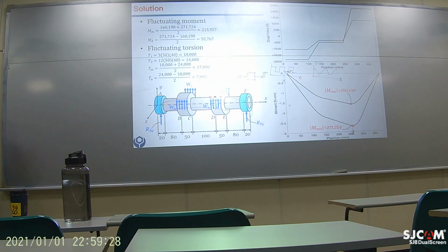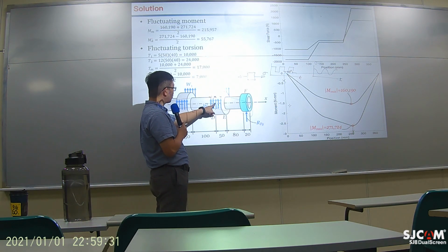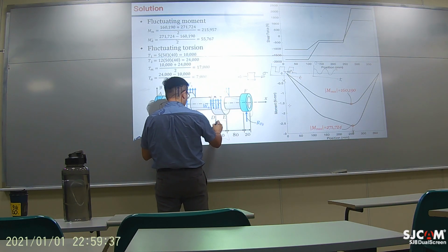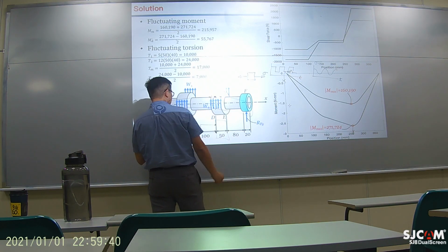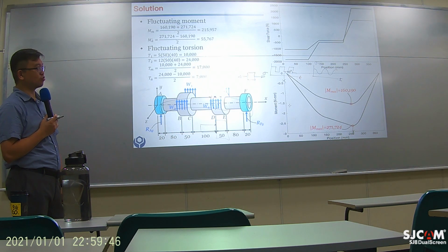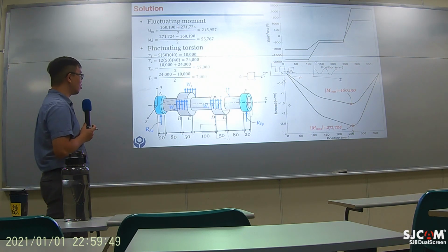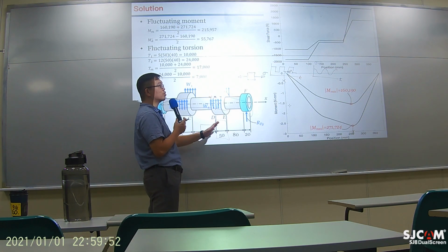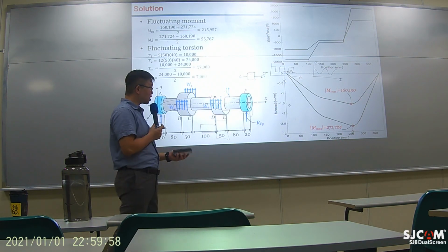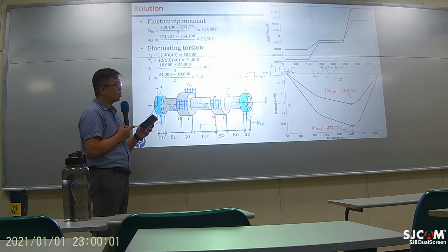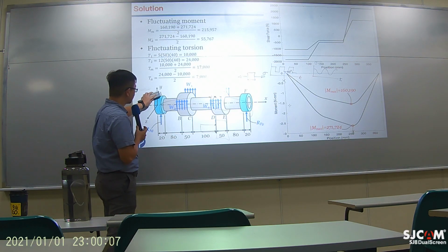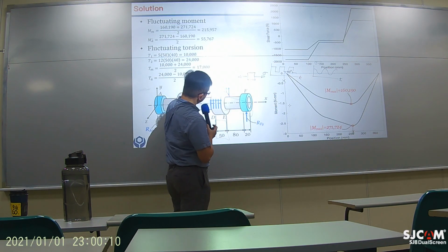But this particular location is right at this area, like right at the corner. So yesterday we mentioned there could be an effect of stress concentration. So let's just assume the location is right at the corner, and let's just use the table to figure out the stress concentration factor and study how much larger the stress is going to be due to the effect of stress concentration.